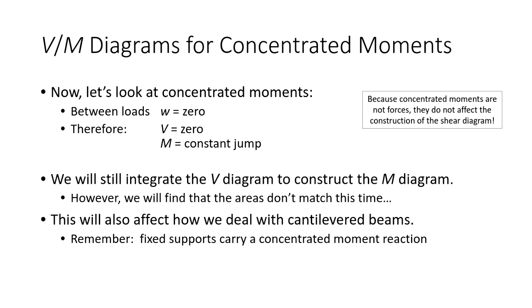Now, a concentrated moment is just that. It is a moment, okay? So it's not a force. So when you look at concentrated moments between the loads, there's zero force applied, so there's no change in the shear diagram at all. It's not a force. So when you're drawing your shear diagram, you kind of ignore the concentrated moments.